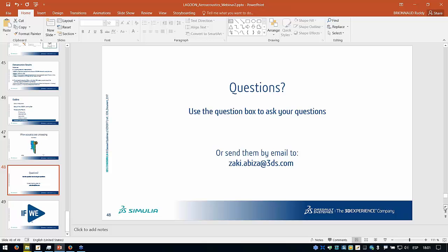Yeah, thank you for this answer. We have another question from an attendee asking about the reflection from the boundaries. How does XFlow deal with the reflection from the boundaries? Yeah, that's a very good question. In this case, I didn't speak about this because we're in an external configuration. So you don't have many problems with reflection at boundaries because the domain is large and the resolution gets coarser and coarser, so you diffuse everything when you get far enough. So there's no problem about that.